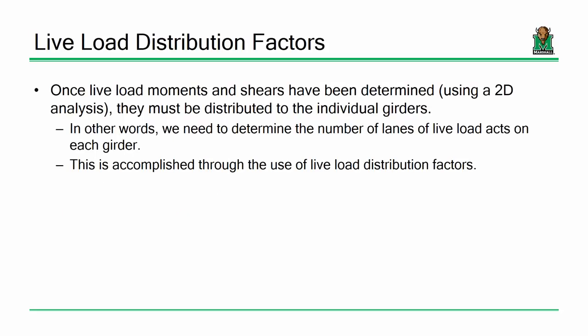So, what's going on here? Well, what we did just now is we talked about the longitudinal placement of a truck. Where do we place that truck along the span to get the maximum force effect at a given point? But what we've got to do is translate that into real life. In other words, what I just did was the triangle and the circle, the line, the mathematical model that we use for structural analysis.